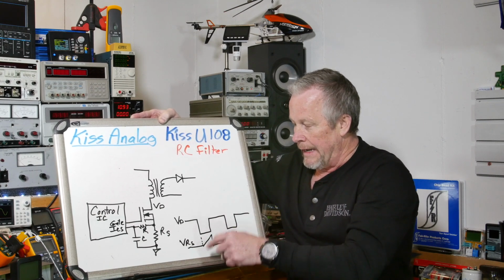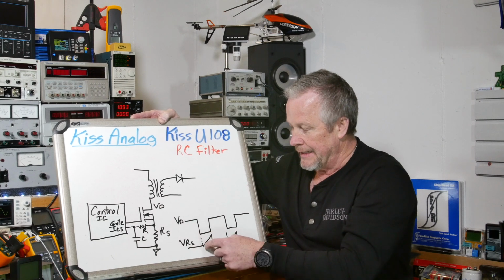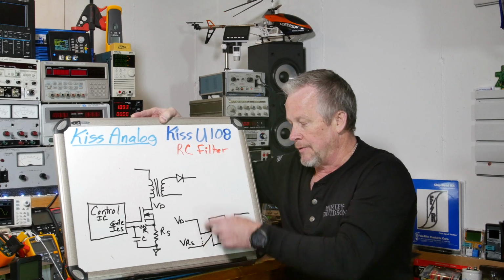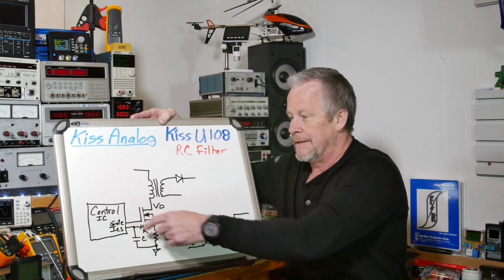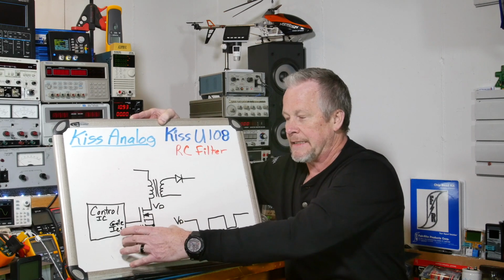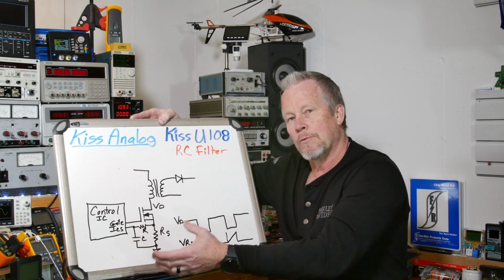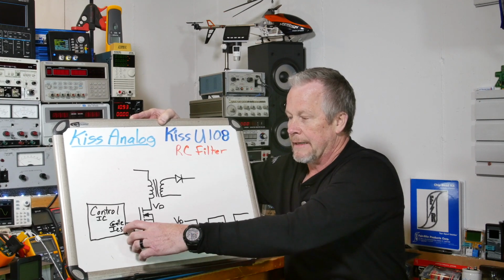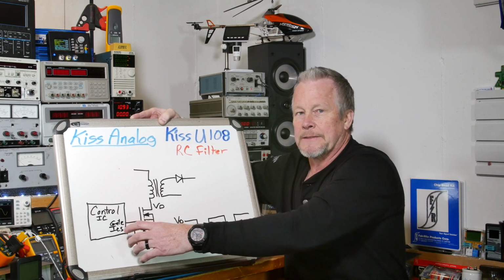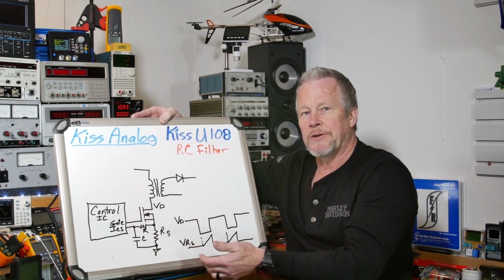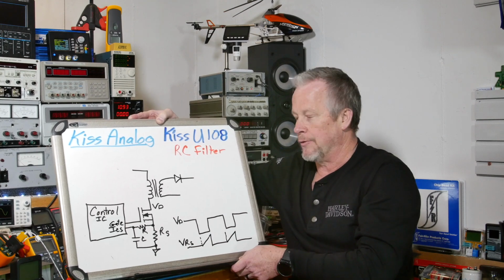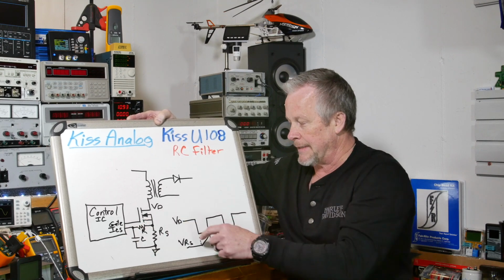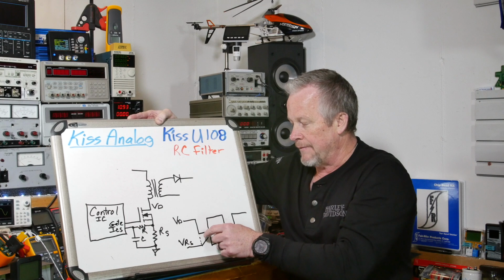And when this FET turns on, it creates a voltage spike, and you don't want this feedback, because on a current mode control, which a lot of power supplies are driven off of, when it looks at that, it's going to see that as, oh, there's my trip point. I just barely turned on. Okay, I'll turn right off again. And you don't want that to happen. So you set up this RC filter, this resistor and this capacitor, to smooth off that first transition.